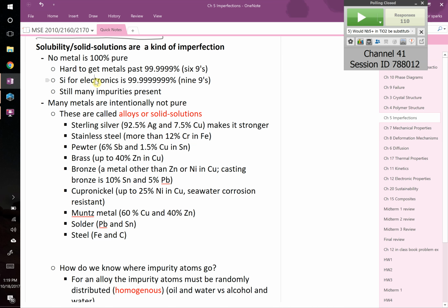And then they apply a very careful voltage so that only the copper atoms will dissolve from one side, go into solution, and plate on the other side, but not the other atoms. So antimony, bismuth, and other stuff that they don't want will crash down into the solution and sit at the bottom of your electrolyte. That's one way. There's lots and lots of others, and we just won't get into them in this class. Okay?